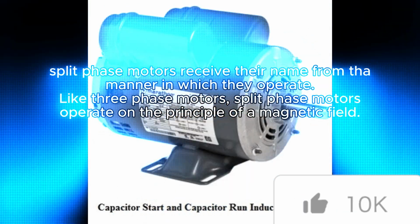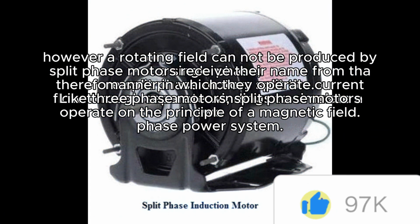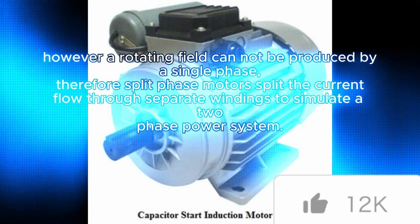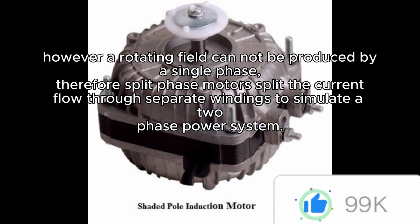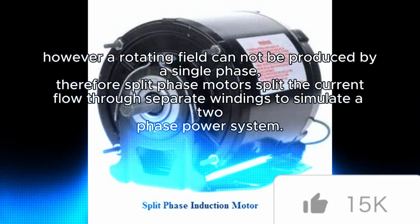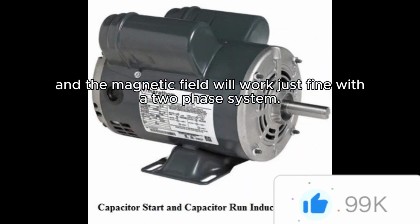Like three-phase motors, split-phase motors operate on the principle of a rotating magnetic field. However, a rotating field cannot be produced by a single phase. Therefore, split-phase motors split the current flow through separate windings to simulate a two-phase power system, and the magnetic field will work just fine with a two-phase system.